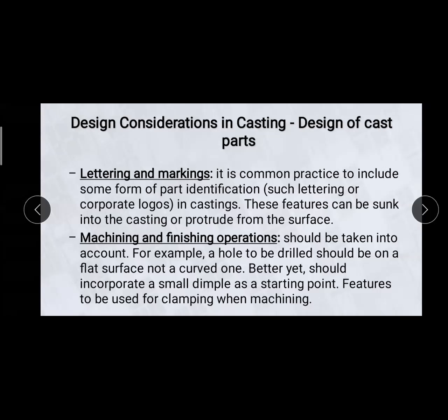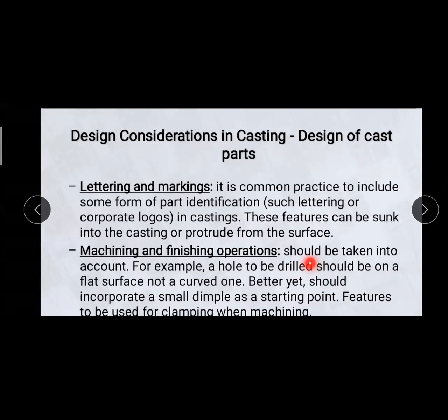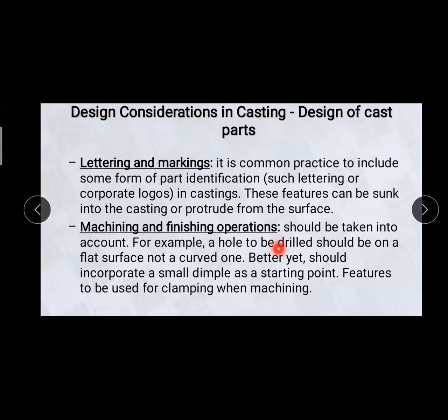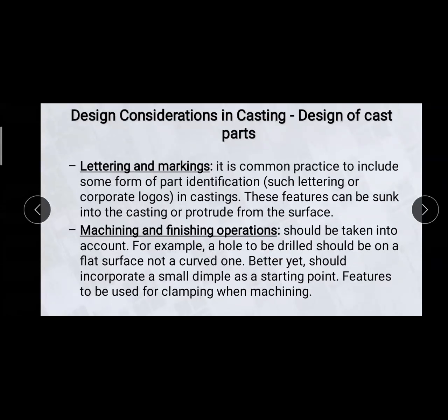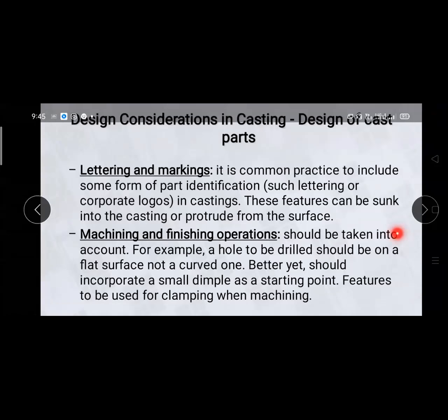Okay. So the machining and finishing operations should be taken into account. For example, a hole to be drilled should be on a flat surface, not a curved one. Better yet, the design should incorporate a small dimple as a starting point, and features to be used for clamping when machining.